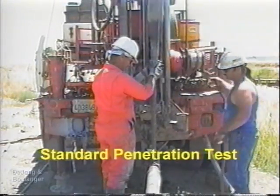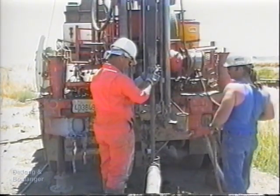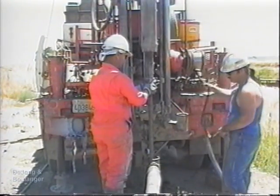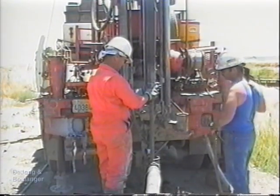A relatively simple and standardized method for estimating the compactness or stiffness of the soil in situ is the Standard Penetration Test, or SPT. This test consists of counting the number of blows of the hammer required to drive the split-spoon sampler a specified distance into the ground.